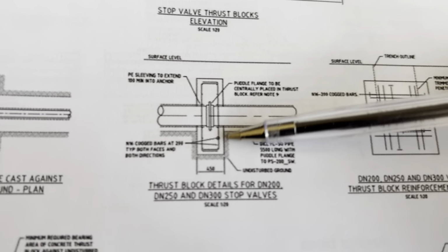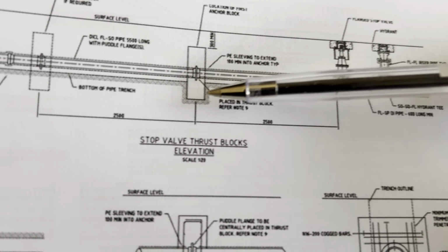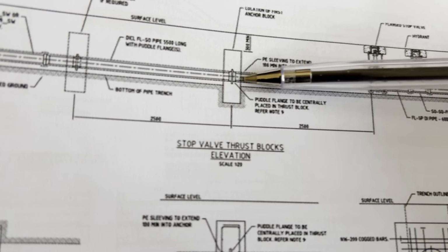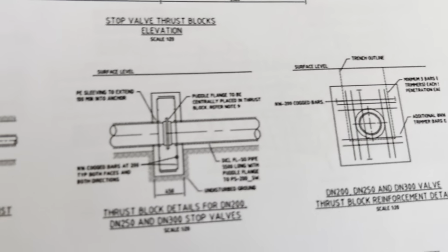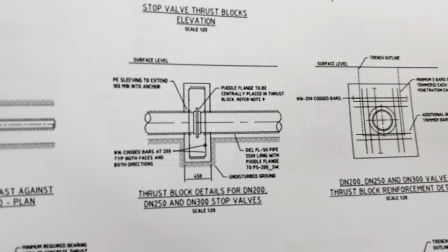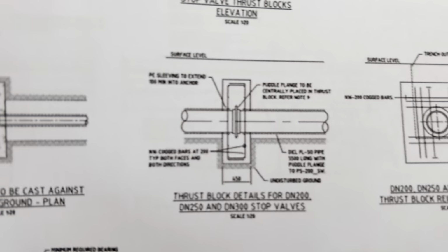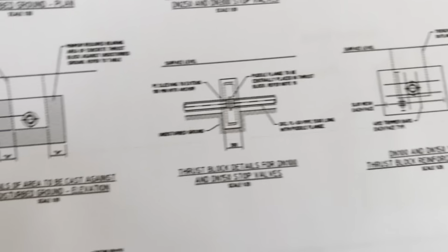And remember, for the first part that we're going to check against the soil capacity, we always use the service limit, that is, the thrust load is unfactored. But for the design of this concrete block, we're going to have a factored load, and the same principles that we use for, let's say, a bending system or a shear transfer system. It is factored load, and also we decrease the capacity of the system to design. That is the general thing, and same here.